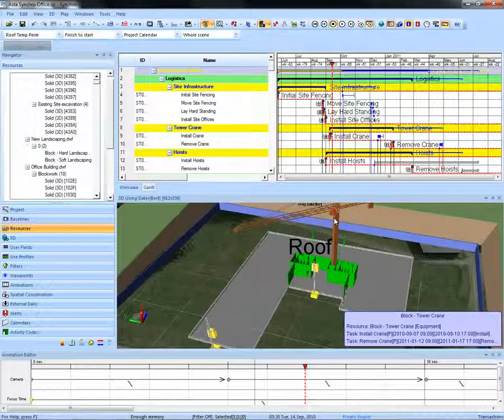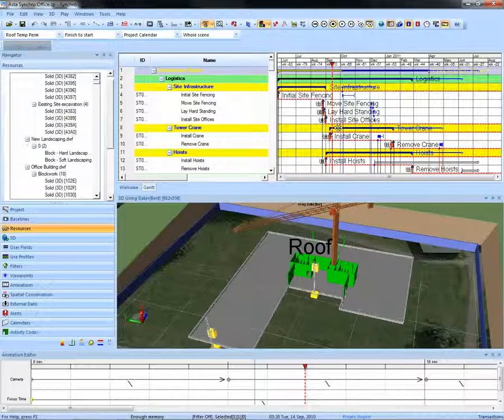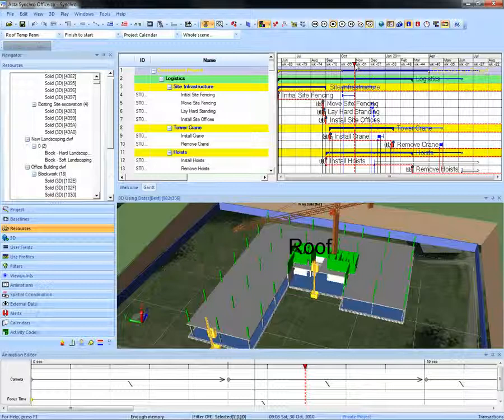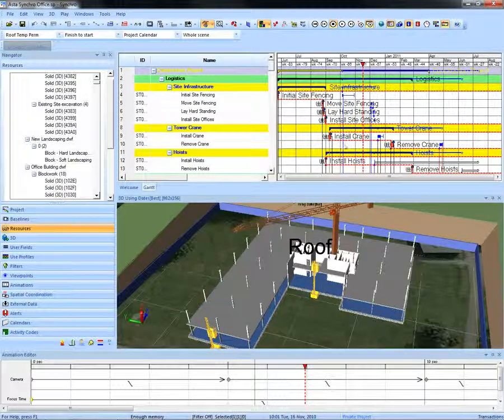So as I say, the linking between the time element and the 3D object is part of BIM, one of the levels of BIM, which is called 4D, 4 dimensions. So it's very useful for seeing how the building is being built up by time. And some of these applications like Synchro have got nice video capabilities, so they can be used in all parts of the construction period. And obviously possibly BIM thereafter is for facilities management and asset management.